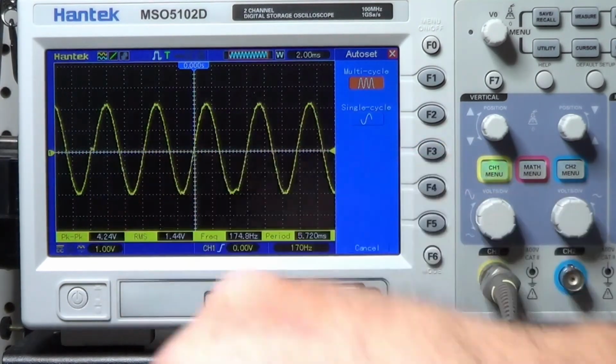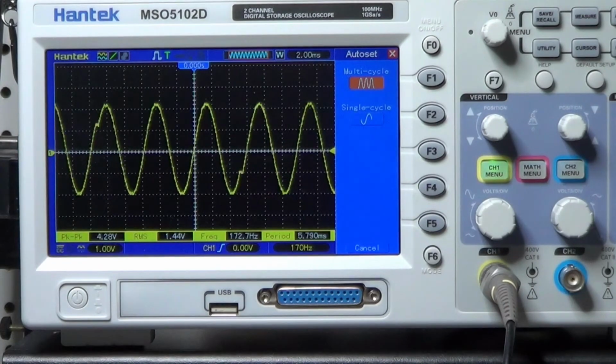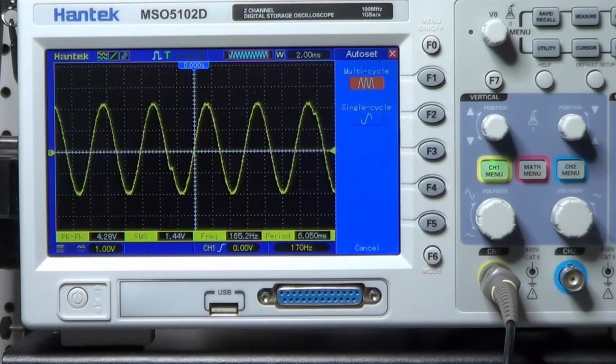There is some wobbling over here, probably because we are still using the delay function for actually outputting the signal out of the Arduino. Okay, it looks like this prototype works a little better than the first one, but the frequency of the signal still cannot be increased much. Fortunately, we still have some space for another improvement, eliminating entirely the use of the delay function. Let's see how this can be done.